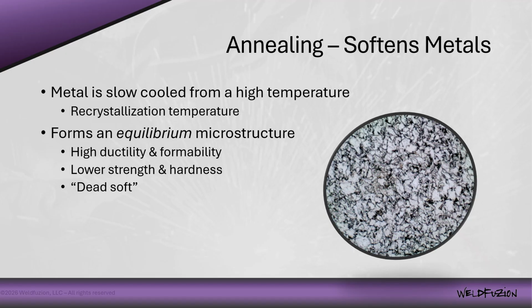On the other hand, some alloys are supplied in the heat treated condition. So you're going to get that material in with some form of heat treatment done on it, right? And it's important to understand what you're working with, especially if it's a heat treatable alloy. And we'll discuss those with each material module. And if we don't pay attention, we could be having some serious issues with our after welded results.